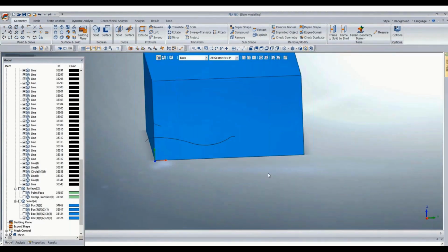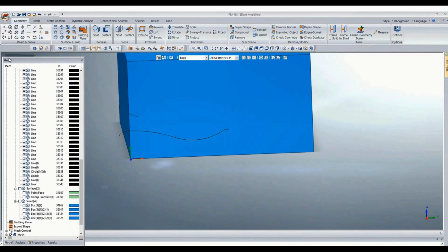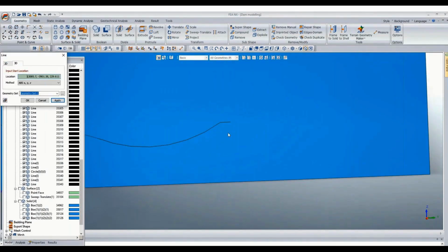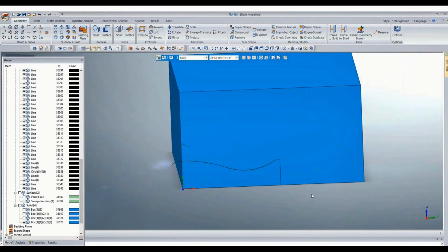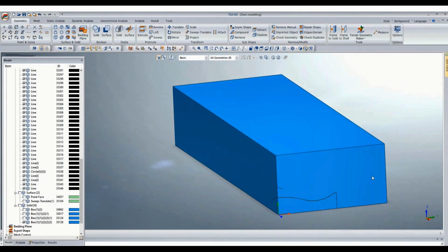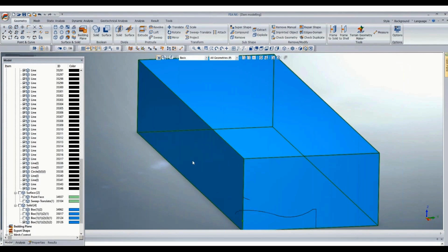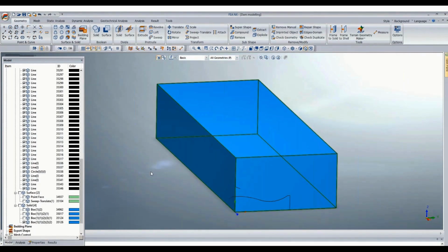Okay, and I can create a perpendicular line from here. You will find that normally we will require about 10.5 meters towards the upstream side from the dam axis for sufficient space for the stop log groove, for operating those stop logs, and for that pier profile.